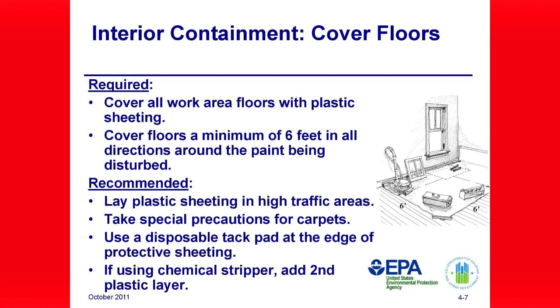Consider covering shoes with a removable shoe cover, wiping off the tops of the shoes and soles of the shoes with a damp paper towel each time you step off sheathing, or using a disposable tack pad can remove the dust from the soles. Immediately place used paper towels in a covered garbage bin. A tack pad is a sticky pad that you walk on to remove dust from the soles of your shoes. They are disposable and should be changed daily.